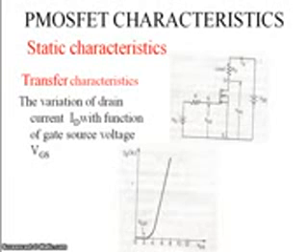Here is the threshold voltage VGST. The threshold voltage VGST is the minimum positive voltage between the gate and source to induce the N channel. Thus, for gate voltage below VGST, the device is in the off state. The magnitude of VGST is of the order of 2 to 3 volts.